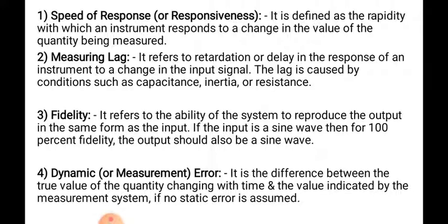Then next one is the measuring lag. The name itself suggests that there will be certain lag in giving the output after getting the input. It refers to retardation or delay in the response of an instrument to a change in the input signal. Measuring lag is how much delay or retardation there is in giving the response to a change in the input signal.